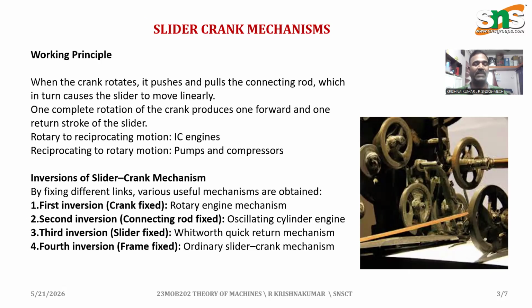Inversions of slider crank mechanism. By fixing different links, various useful mechanisms are obtained. First inversion, crank fixed: rotary engine mechanism. Second inversion, connecting rod fixed: oscillating cylinder engine. Third inversion, slider fixed: whitworth quick return mechanism. Fourth inversion, frame fixed: ordinary slider crank mechanism.